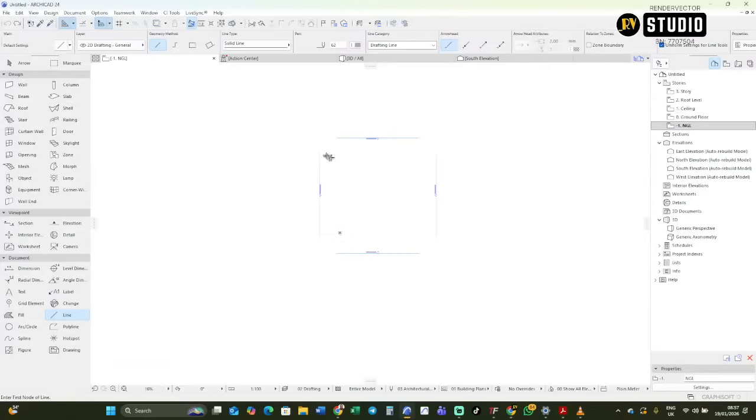All right. So I'm going to bring out 41. It says 41, but that's 41,000. So when I drop the line, while going down, I'm not going to be accurately straight, so I have to hold down my shift. When I hold down my shift and press the D for dimension, so now I press D, it's locked in, like give me a command. So dimension, instead of 41, I'm going 41,000. So we're working in millimeters here.